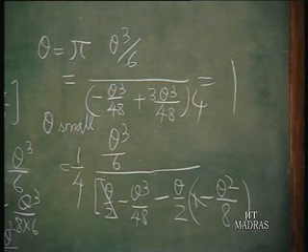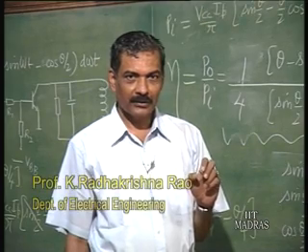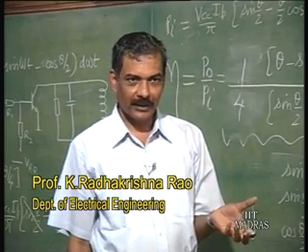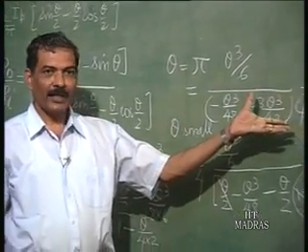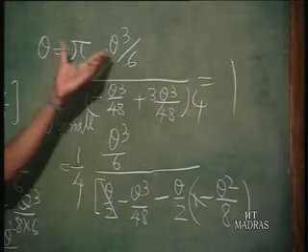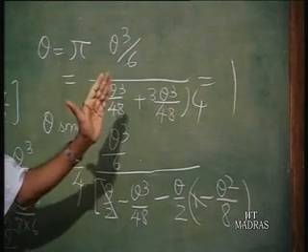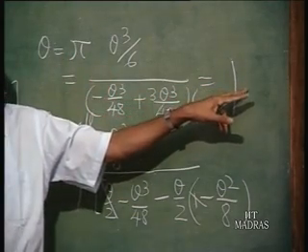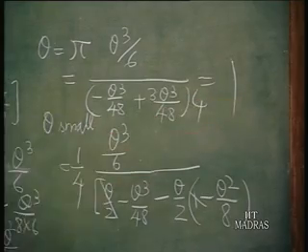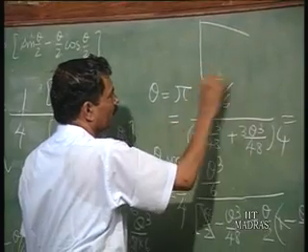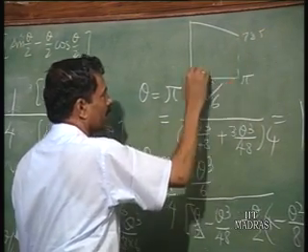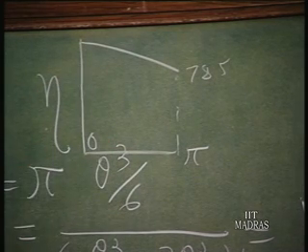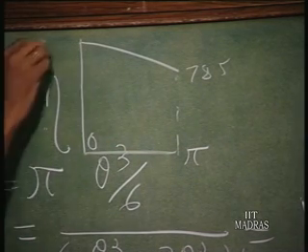This is the theoretical efficiency. Of course, this is not possible because you cannot make theta equal to 0, because a certain amount of power has to be given. Theta has to be non-zero, and therefore it cannot be 100%, it is always less than 100%, because theta cannot be made equal to 0. Theta going towards 0, efficiency is very nearly equal to 100%. So, it is going to decrease from 100% up to 78.5 for theta equal to 5. So, this is 100%.